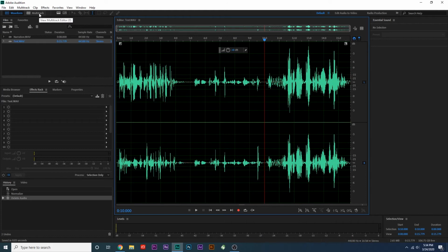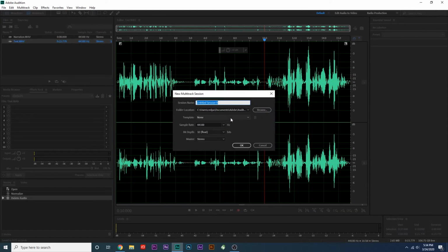So I'm just going to click that, and this window will pop up asking the name and location. You can name the session whatever you want, but what we also need to look for is the sample rate. It's set at 44.1 kilohertz, or just 44,100 hertz. The reason why we want it set to this, because Audition's default is actually 48 kilohertz instead of 44.1,